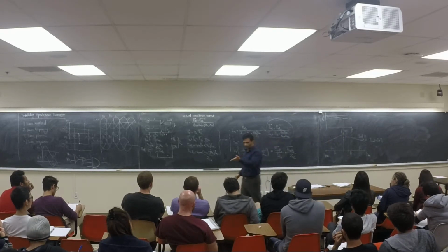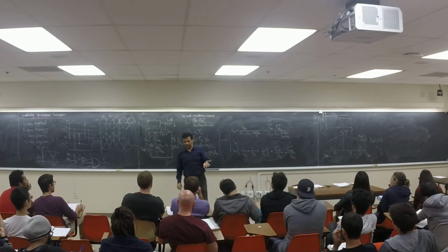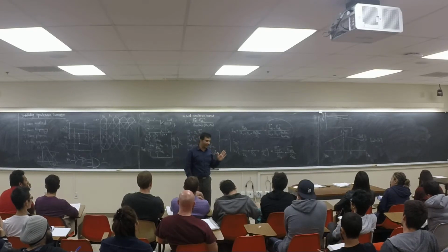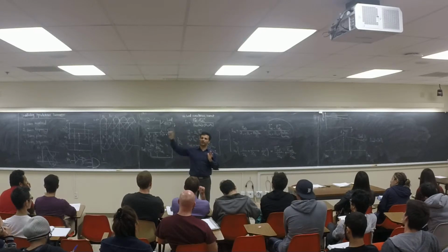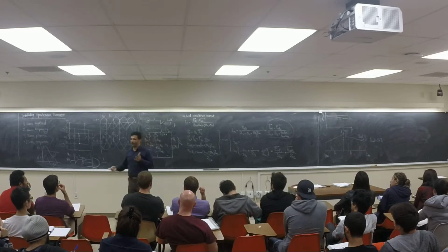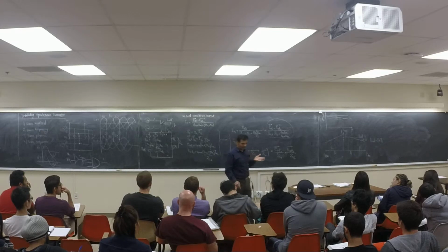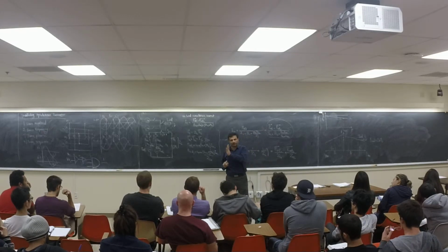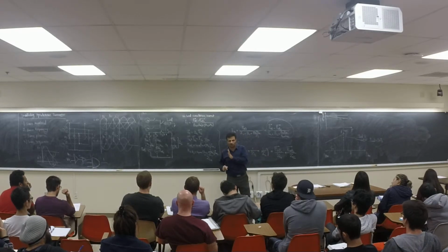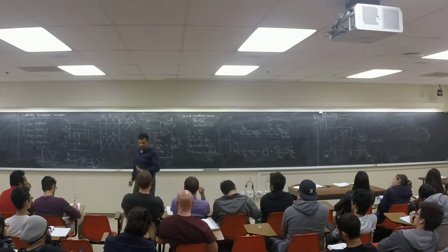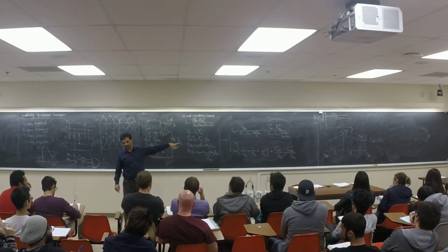Have you measured the frequency of the grid? It's not perfectly 60 if you have accurate measurement. It does change at any time, but not to, for example, 59 or 61. It's going to go maybe in the third digit or the second digit of the frequency. Maybe it's 60.05, 60.06, 60.009, you know what I'm saying? There's going to be some changes, but it's usually after the second digit. You have to have a very, very huge load to change the frequency. This is a concept of paralleling based on this characteristic.